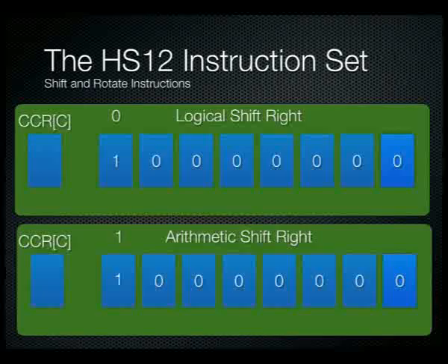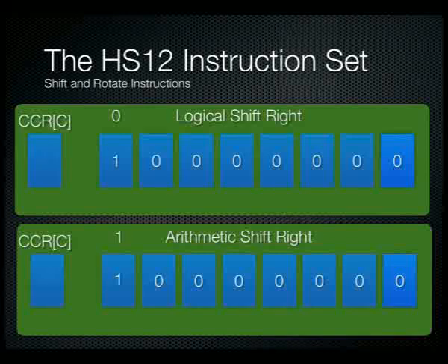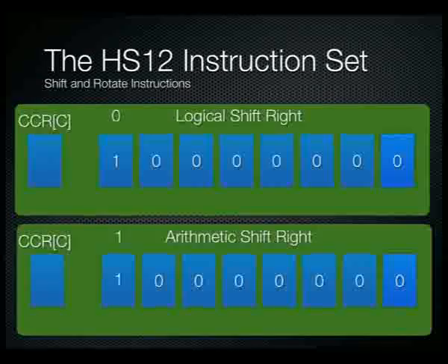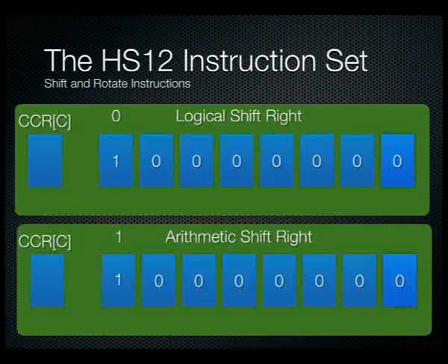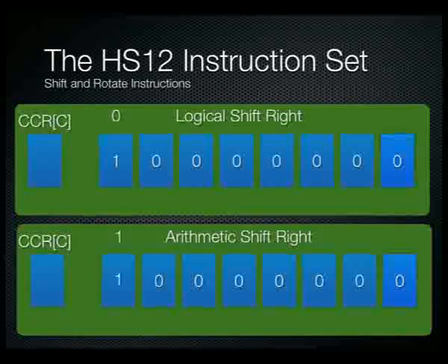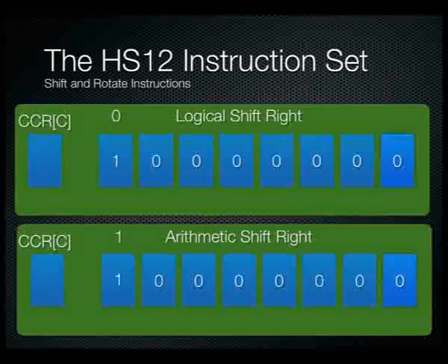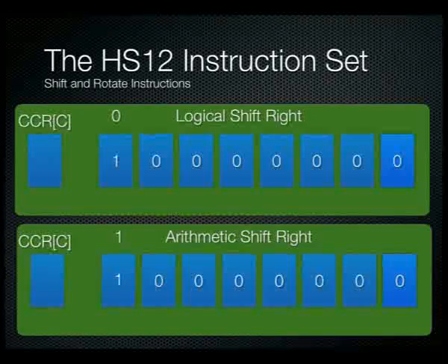Okay, so if you do a logical shift right of a negative number, what logical shifting does is it zero pads the front. So you can see in the slide here we have a 0 sitting above that bit ready to slip in. So if you do a logical shift right of a negative number, effectively a 0 will go on the MSB, the negative number will instantly change to a positive number because the MSB is no longer 1, and the actual magnitude of the number will be all screwed up as well, so it won't even be the right magnitude. So you lose the sign as well as the value, so the number will be corrupted.